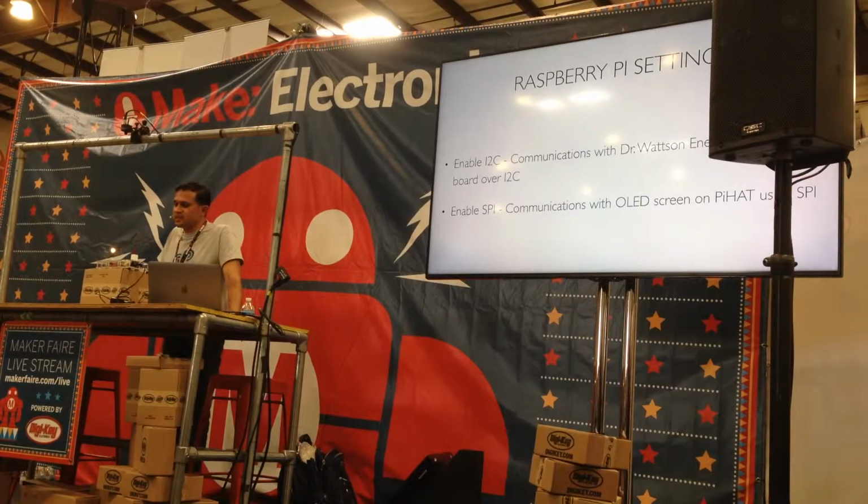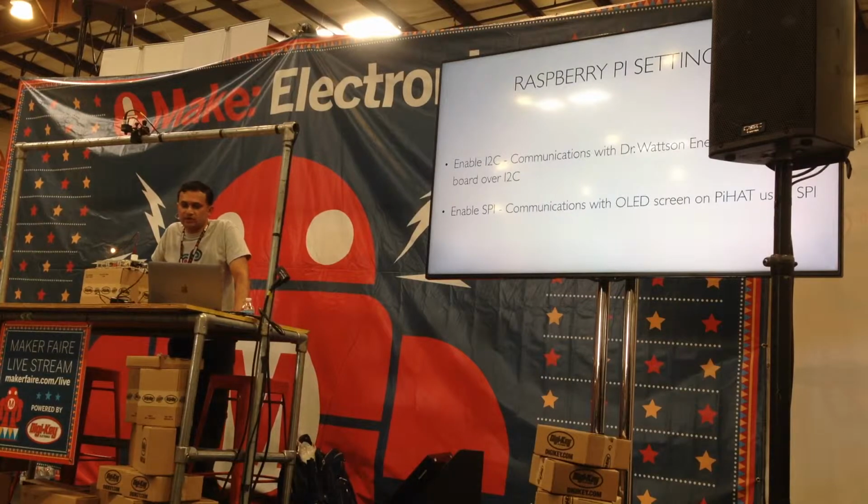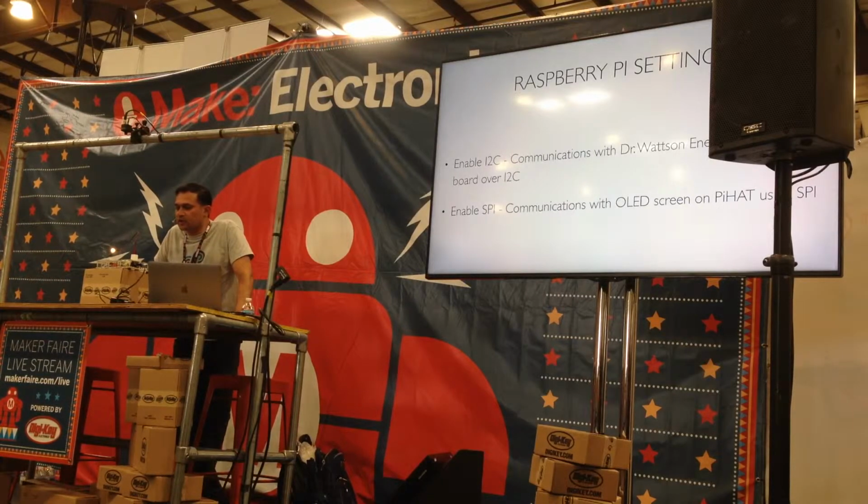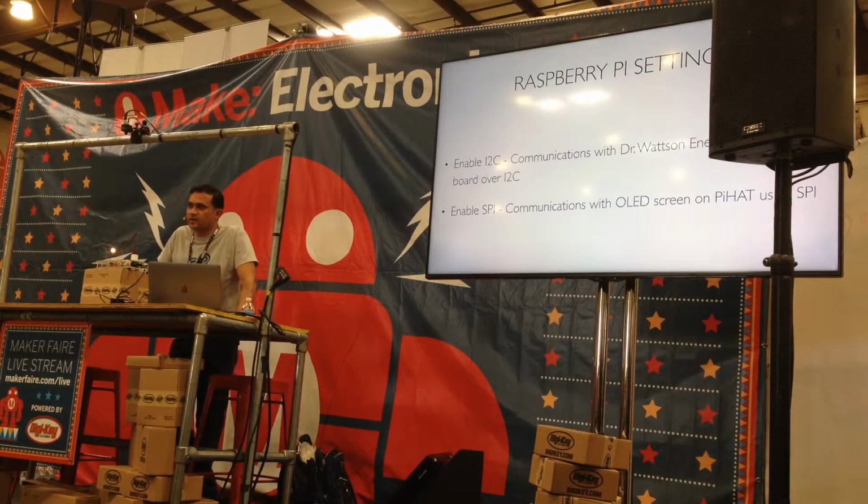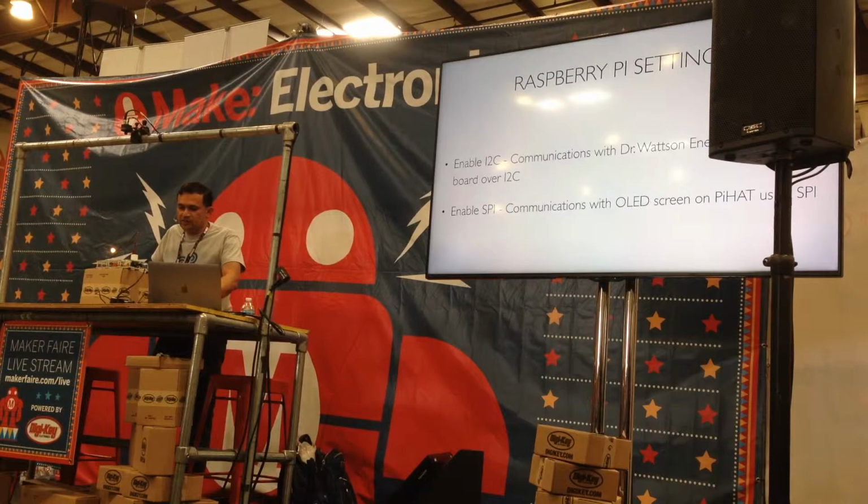And then for the Raspberry Pi, the communication to my energy monitoring board is through I2C, and so you need to enable that. And I've also configured the communication to my OLED screen to be over SPI, so you need to enable that as well.